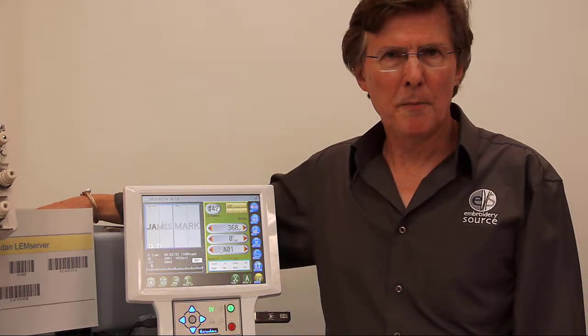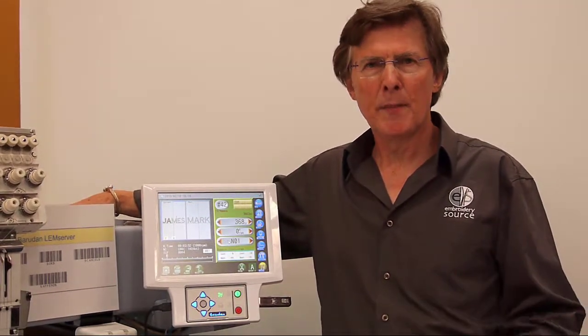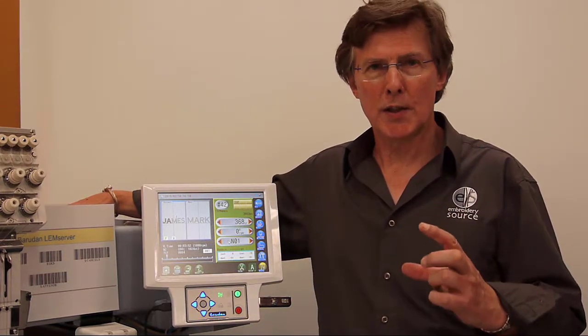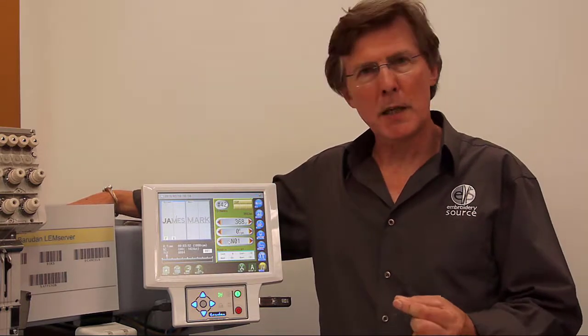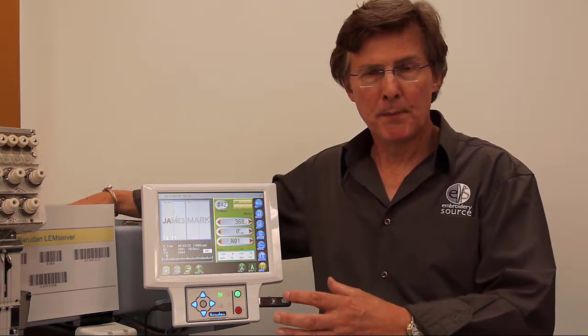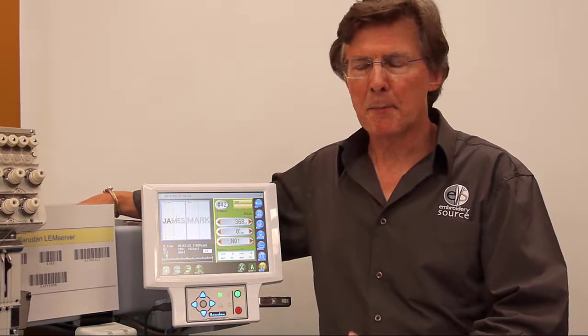If you've never used team names before, how it works is using your embroidery software like Wilcom, you can create a list of names, and that list of names, let's say it starts with Paul, Dave, Sam and Bill, that will be downloaded into your embroidery machine as one single design, and at the end of every name is a stop signal. So the idea being, you start the machine, it will embroider the first name and then the machine will stop. You take out the garments, put in the next set of garments, that embroiders the next name.